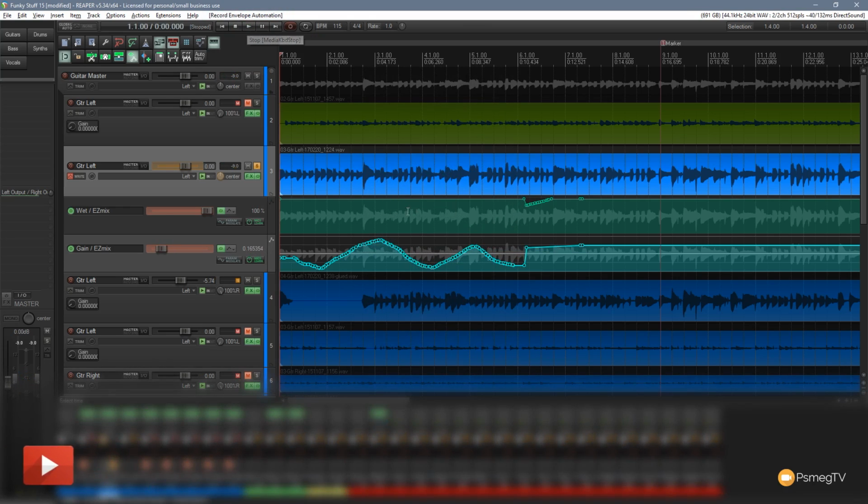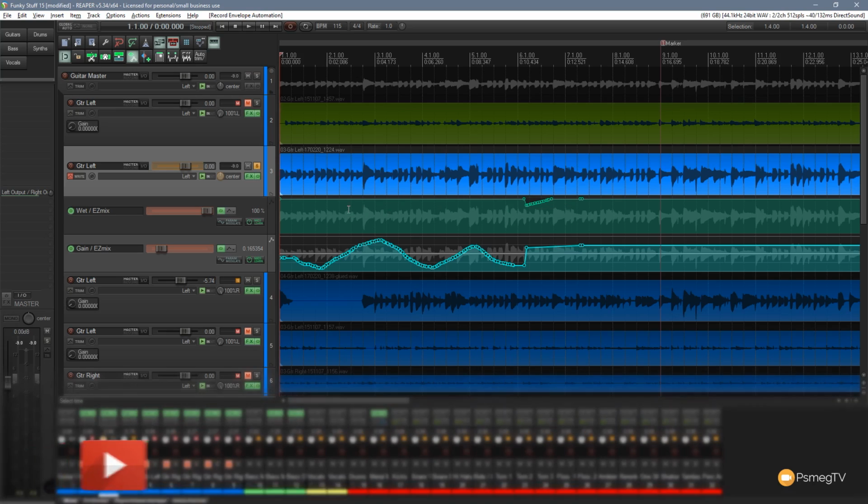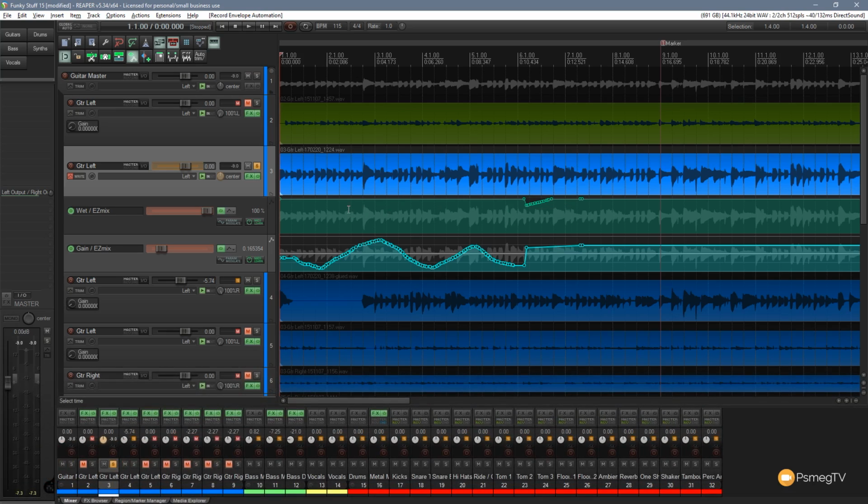now there's one thing you notice there, that this track is also recording, and because we're not making any changes to that, it's overwriting everything we've done previously. Now that's not something you really want to happen. You may want to do like I've done, where you've got multiple different parameters that you want to affect, but you want to build them up one at a time. Well, the last thing you want to do is to end up overwriting the previous things. So let's take a look at how we can disable that problem.